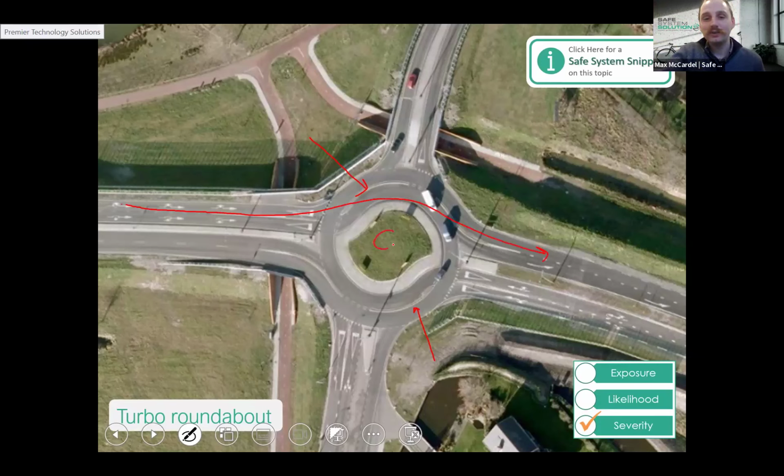If you make this radius too small, then drivers can just go straight through. So that's what that previous graph was talking about. The idea of the turbo roundabout is because you've got these channelized islands, which is just back-to-back curb, it's forcing drivers to actually use the radius of the roundabout, washing off the speed. There are examples of these installed in Australia if you're interested.